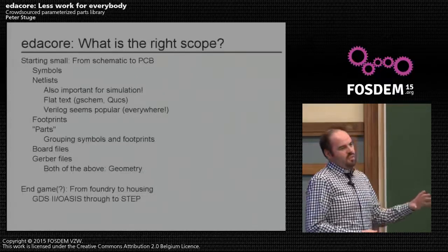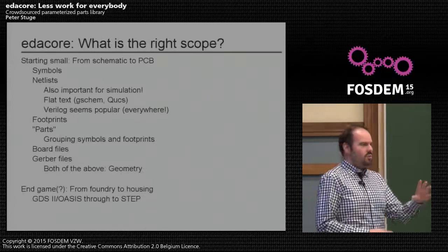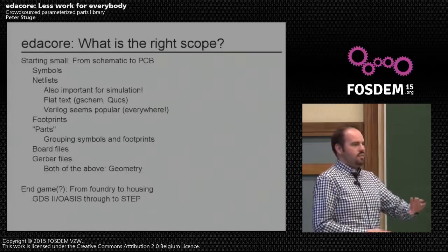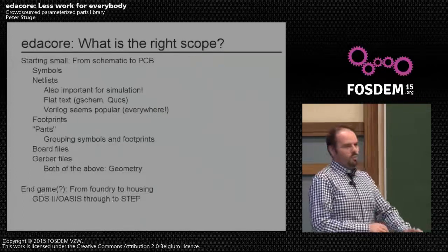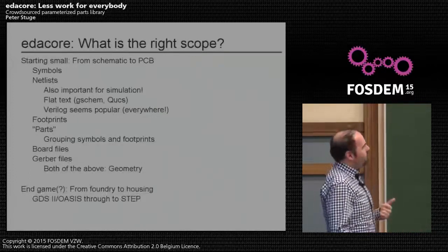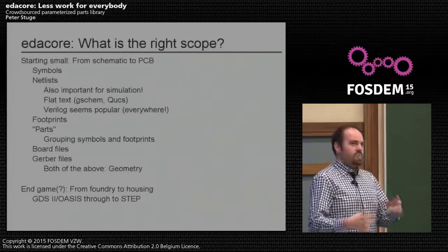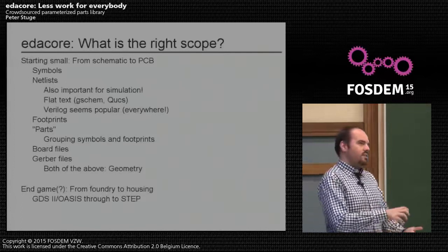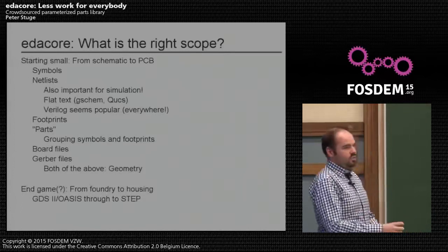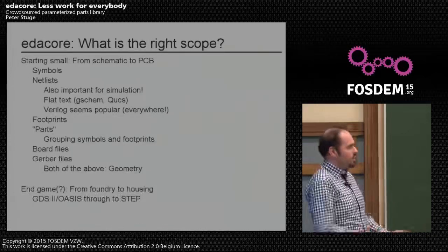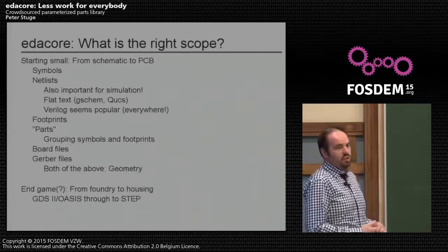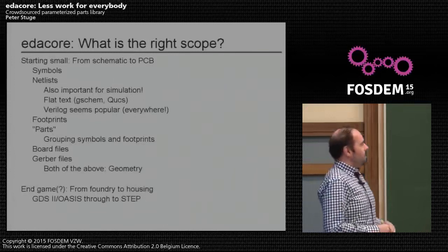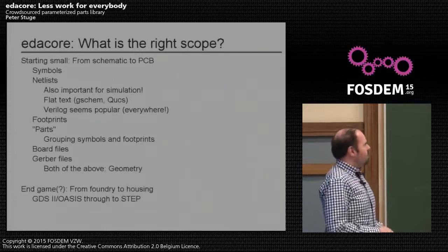If you have in the schematic, you want to say, I'm using this IC, but at that point you don't care what package it is. In the board layout, you do. Still, this needs to be the same. It is the same circuit. So for simulation, you don't want to have two different ones. You want to still have just one. And the vendor will also probably only have one model for this. So yes, need to keep this in mind.